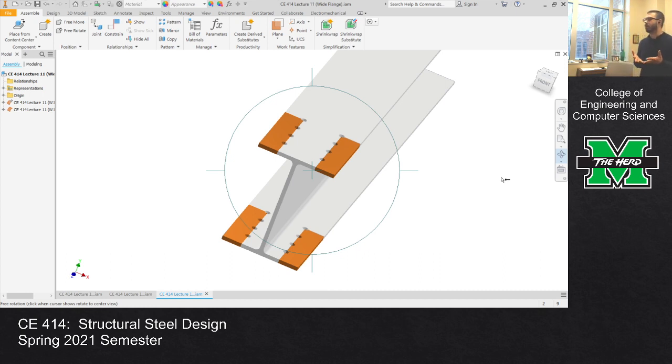What I'd say for this is that the cumulative capacity of this section in block shear is the capacity of all of those. You probably wouldn't find a scenario where one of the blocks would fail without the others. If there was a flaw and one of those blocks were to fail, that would cause such a dramatic increase in load on all the others that they probably all fail at the same time. So for practical purposes, looking at it member by member, we can just assume the whole thing's going to fail all at once.